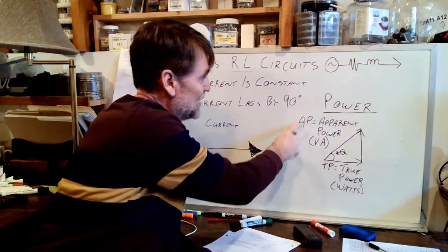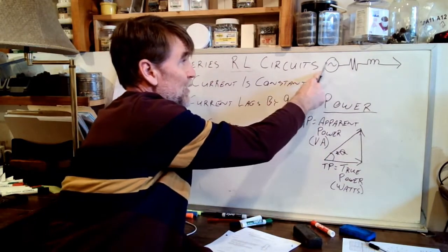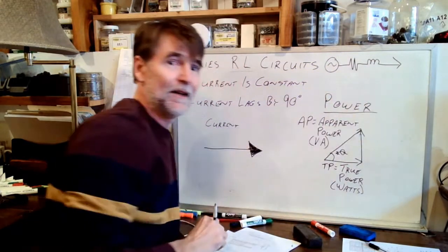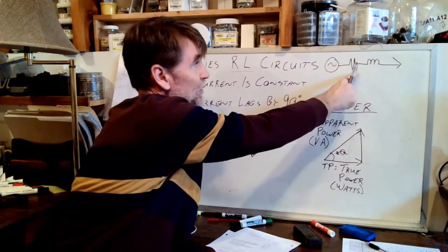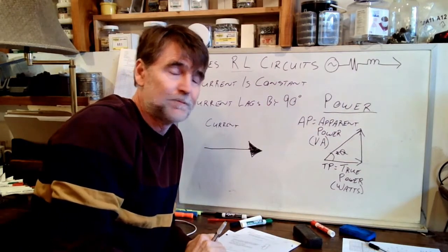And this is why we must size our transformer in volt amps and not watts, because the transformer is the power supply. It must provide power for the entire circuit. It would not be big enough if it was sized to provide power for just part of the circuit.